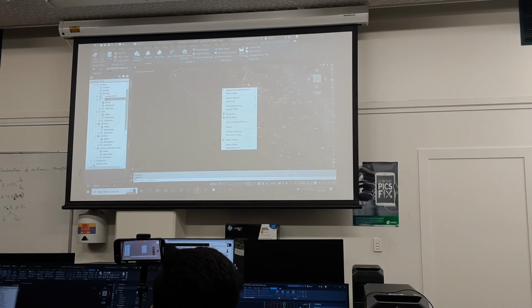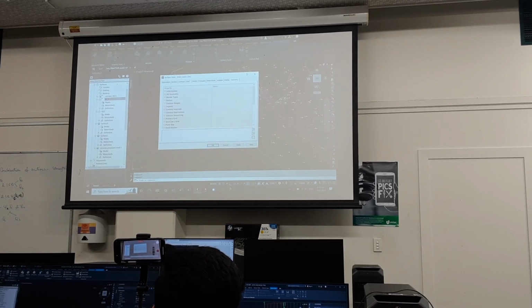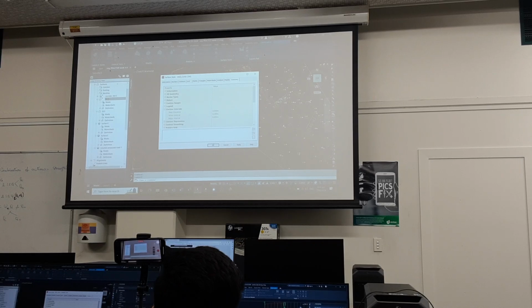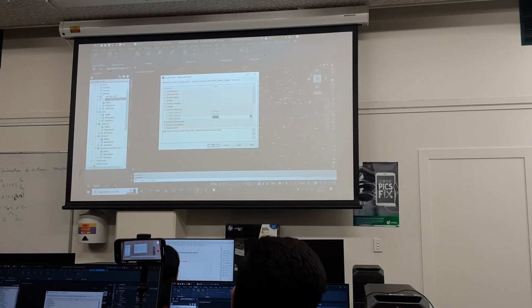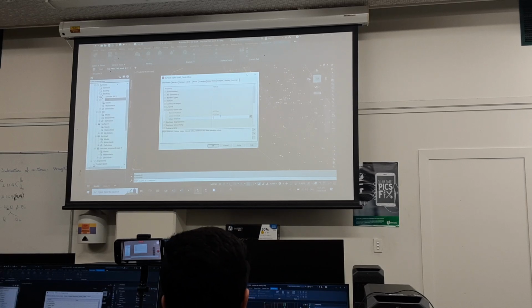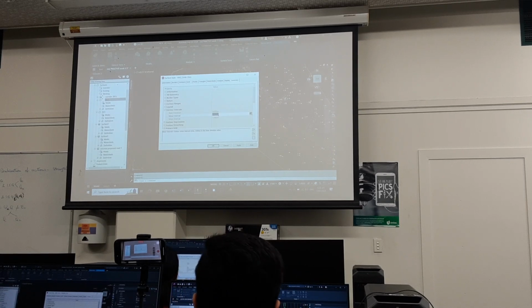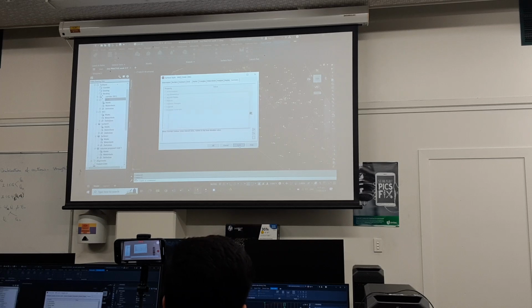So we're going to right click on EG1, edit surface styles, and in the same summary, we go to the contour intervals, and you'll notice the contour intervals has a minor of 0.2 and a major of 0.4. I would like to see a major of 1 on your assignment and 0.2 as the minor. I'm going to go apply, and I'm going to go OK.